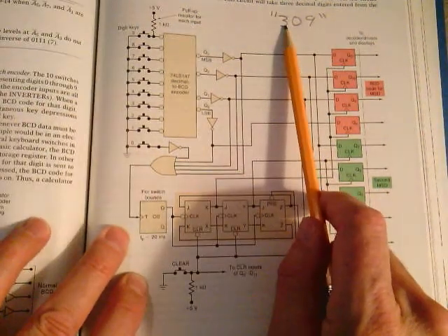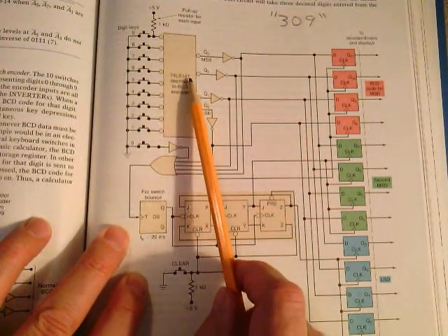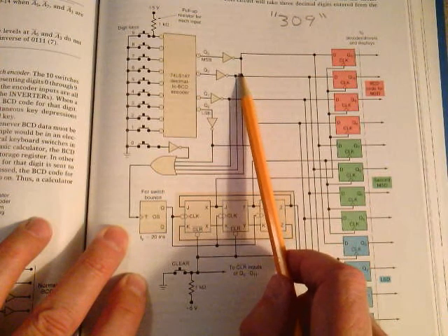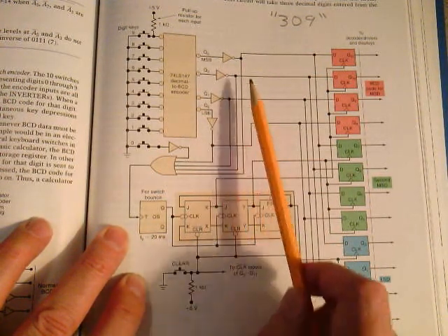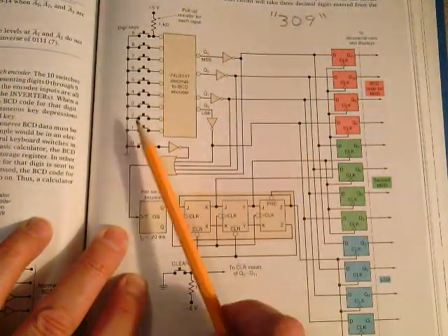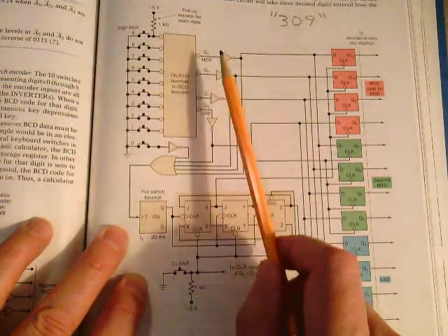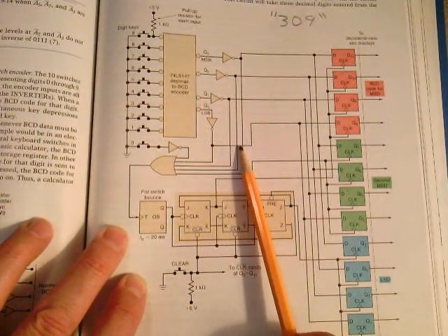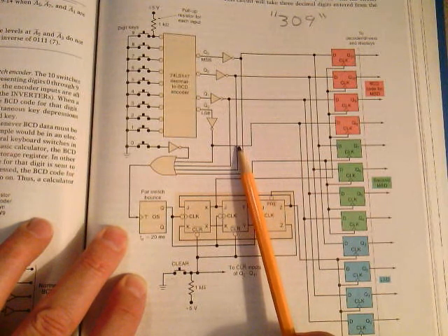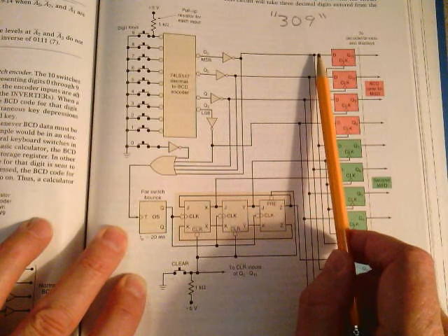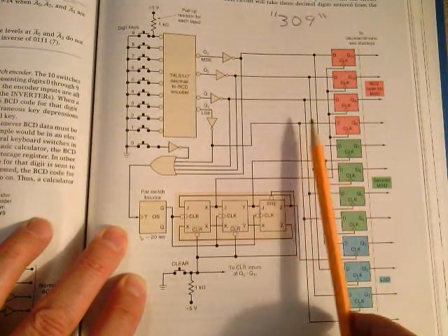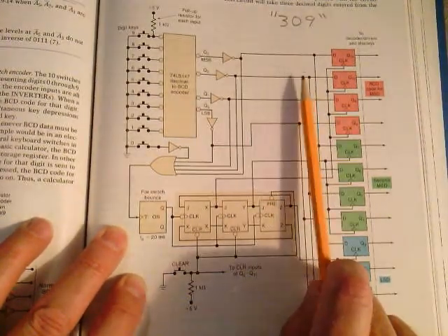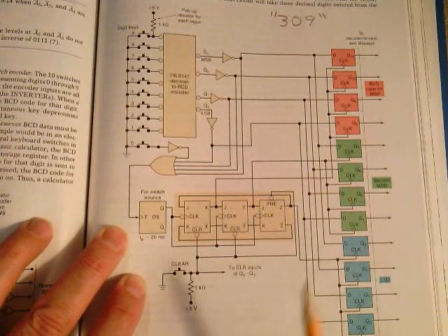The first thing we're going to push is the 3 out here. When you push this 3, you already know how this LS147 works. And I'm not really concerned about the low active. Here's the true outputs right here, with this being the least significant bit and this being the most significant bit up here. So when I push a 3, it's going to put in a 0, 0, 1, 1. That's a 3. Now, this 3 gets set up here as 0, 0, 1, 1, 0, 0, 1, 1, 0, 0, 1, 1. So there's 3 set up for this, 3 set up for this, and 3 set up for this. Only one of them is going to get loaded, though.